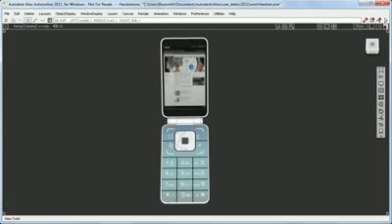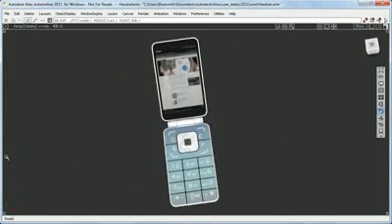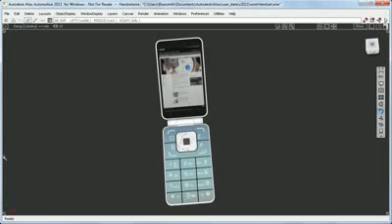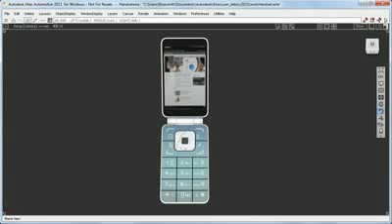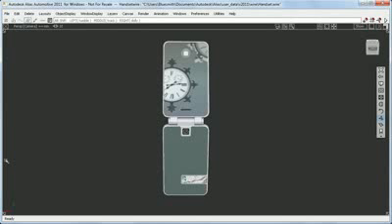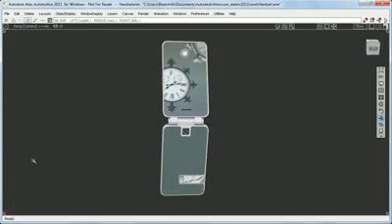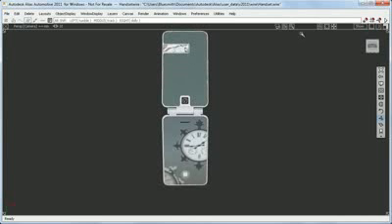View twist turns the view in the viewing plane. If I drag one full screen width to the left, I get 360 degrees of rotation clockwise, and back again I get a full rotation the other way. The azimuth elevation tool turns the camera by 180 degrees, so I can view the back of the product and then the front again. If I drag the full vertical distance on the screen, I still get a consistent movement of 180 degrees.